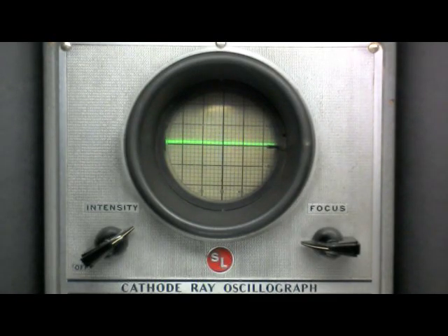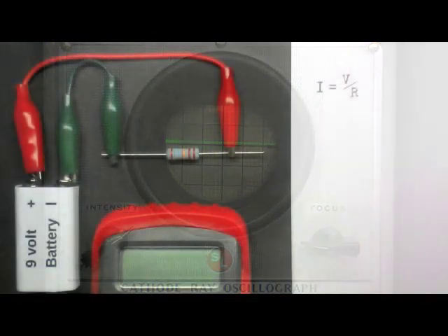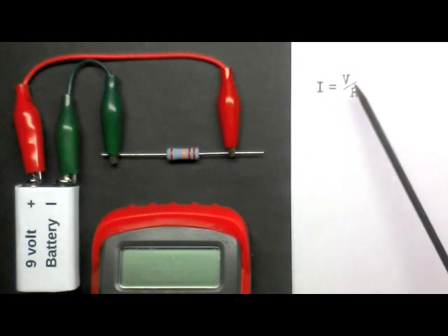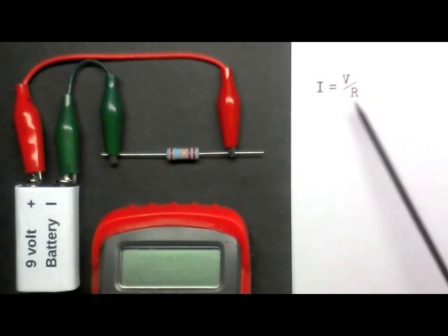Welcome to Scofflaw Laboratories. We're going to look at some circuits, take some measurements, and find the unknown. In this circuit, there's a 9-volt battery and a 22k ohm resistor. Through this circuit, there passes a current. That's the unknown property. We'll get more precise measurements of the battery and the resistor, and then we'll calculate the current. And current equals voltage divided by resistance.